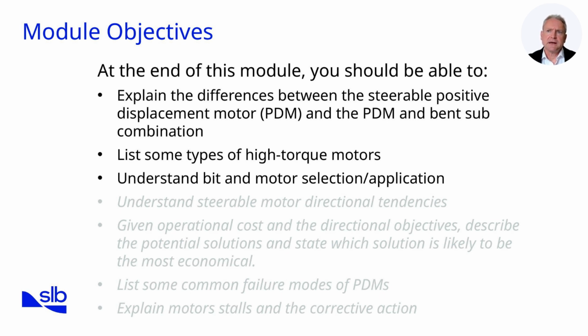In addition, you will gain insights into bearing section designs, contrasting mud-lubricated and oil-lubricated systems, and evaluating their features, costs, and suitability for different environments. We will examine radial bearings and axial bearings, including how hydraulic thrust interacts with weight on bit to determine actual bearing load. You will also learn how to interpret motor performance in terms of RPM, torque, and pressure, and how to read power curves for operational decision-making.